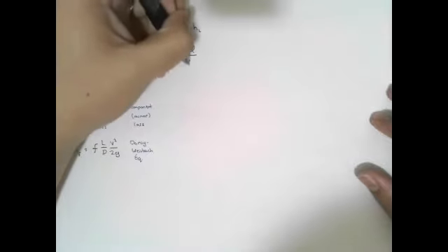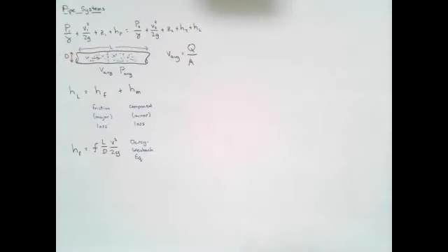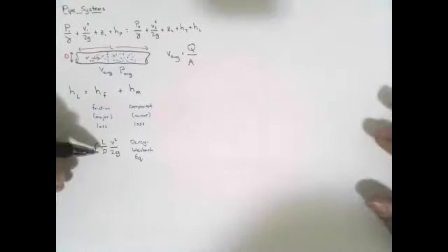Now remember, we're studying turbulent flow. So that velocity v isn't the velocity of any one particle. It's actually the average velocity of that flow. And hopefully we'll remember that the average velocity of a flow is calculated by taking the flow rate and dividing it over the area of that flow. So we're dealing with essentially simplified terms, right? Average velocity, average pressure, and so on.